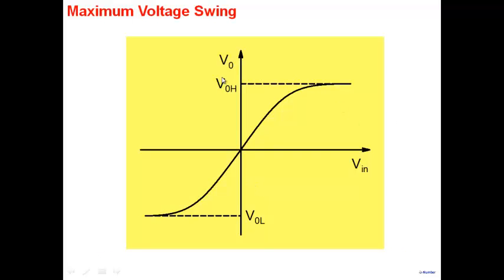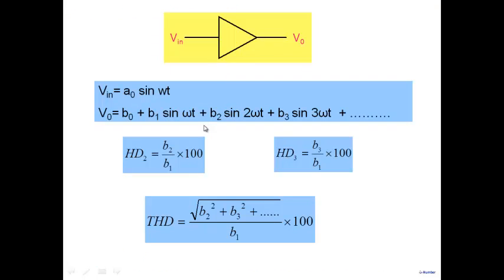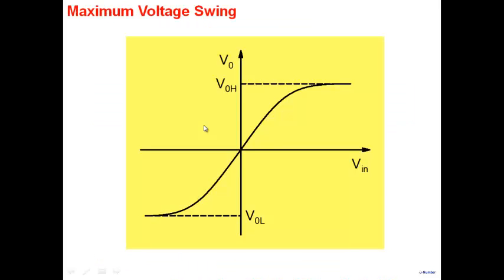This is illustrating another source of distortion here. In the previous case, I was denoting distortion due to the fact that my input is sort of nonlinear. Now, this shows you that when I look at my output versus input graph, I will always get something of this kind. As I keep on increasing my input, my output follows and the slope gives me the gain. But if I keep on increasing, there's a limit to how large my output voltage will go. All of you know that if I take a 741 op amp, I bias it at plus minus 12 volt, then my amplitude cannot exceed 12 volt here, which means I start getting a saturation here, and then I will start getting a saturation here.